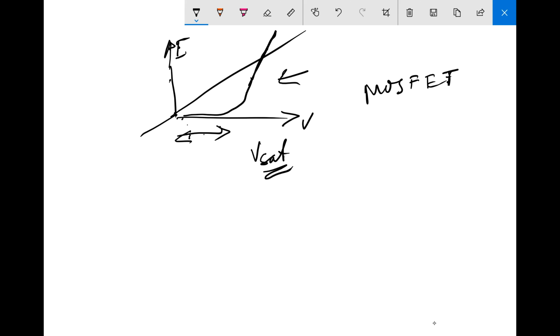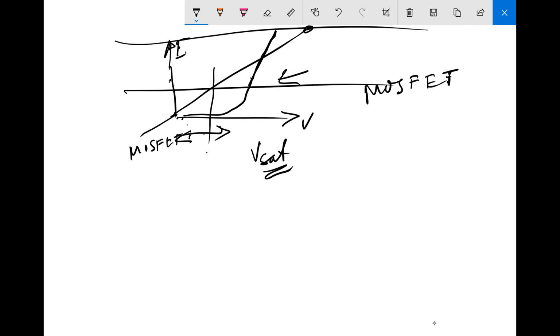And this brings about a very interesting point. If you're at a low current, say here, a MOSFET device will have a lower voltage drop. I'm talking about devices of the same structure and power ratings, etc. But if you go to very high current, like here, the voltage drop on the MOSFET will be higher than that of, say, IGBT.